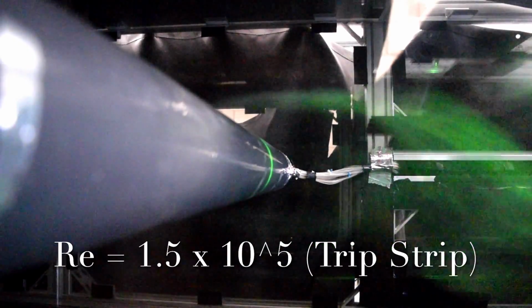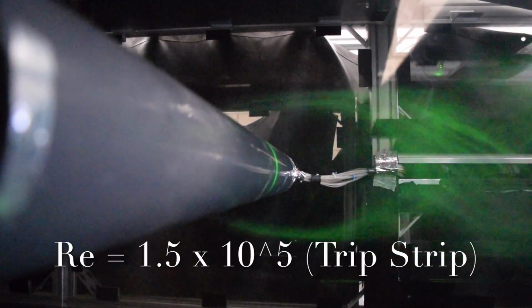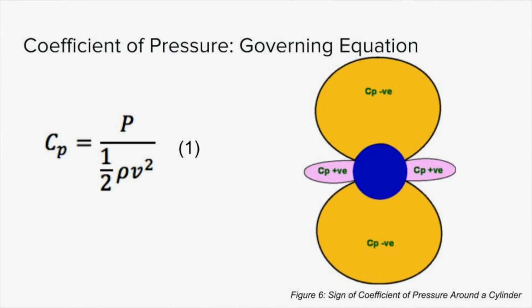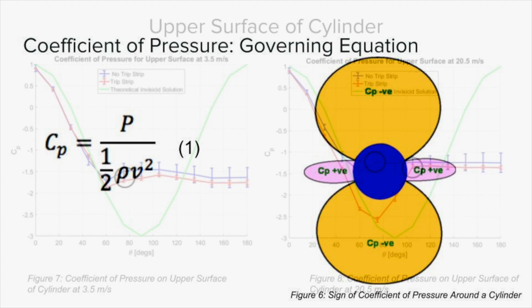At a higher Reynolds number, we can see a larger wake behind the cylinder, resulting in a low pressure region behind the cylinder. To obtain the coefficient of pressure plot, coefficient of pressure was calculated using equation 1. Figure 6 shows that there is a positive coefficient of pressure at the beginning of the cylinder and in the wake region, and a negative coefficient of pressure at the upper and lower surfaces.